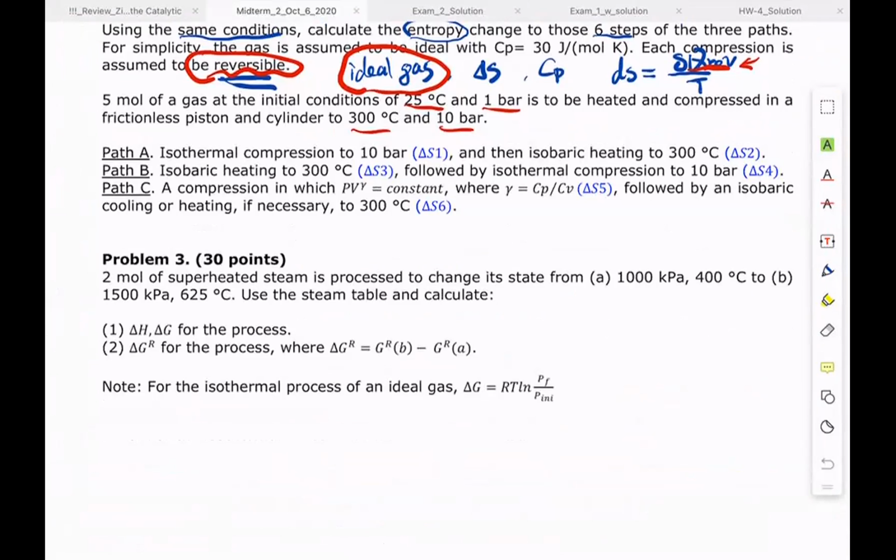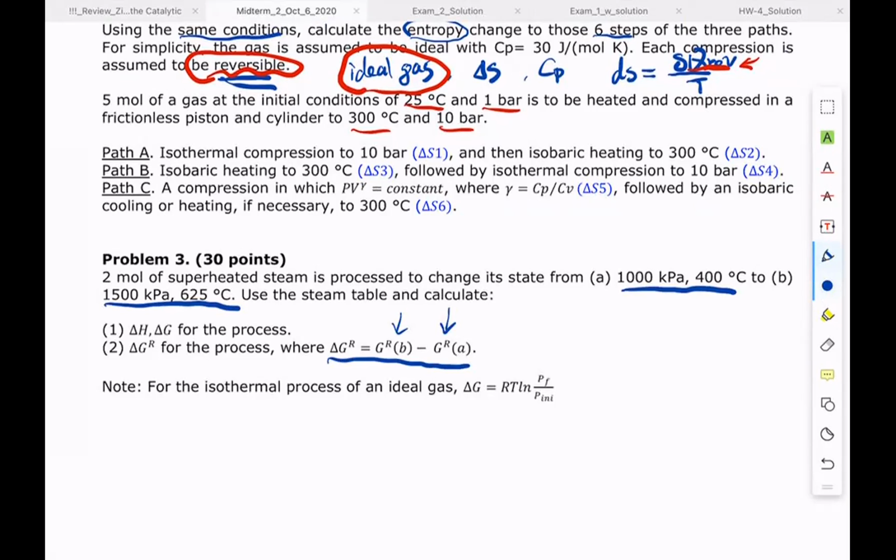This second part is instead of the residual property, I try to understand what is the change of the residual property. So nothing special. You need to calculate the residual property at state 1, at state 2, and try to take a look at the difference. Right. So then first of all, if we need to look at this delta H, then this is HA, and I'm going to have HB. So the delta H is nothing special, which is HB minus HA. The delta G would be the Gibbs energy of state B minus Gibbs energy of state A.